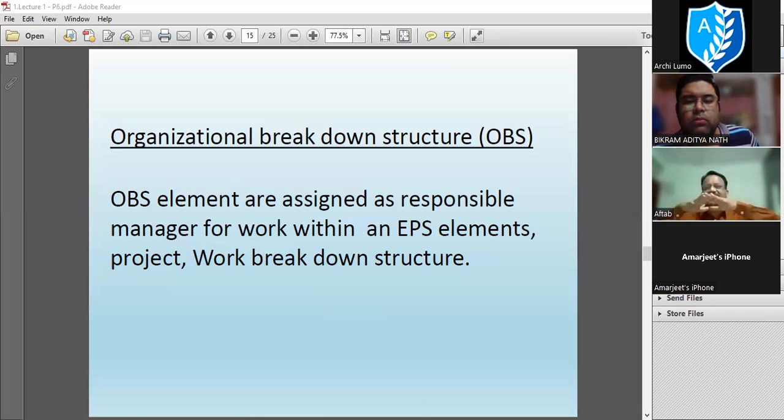No site is cleaned 100%. So you cannot go for excavation and all these things in any uncleaned or undulated plot. So you have to put grader, excavator, all these things to make grading as per your architectural levels, architecture survey levels.